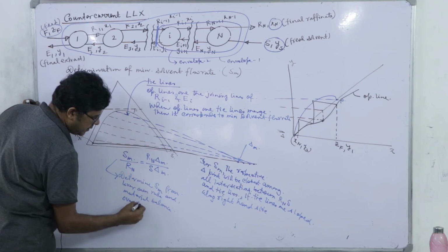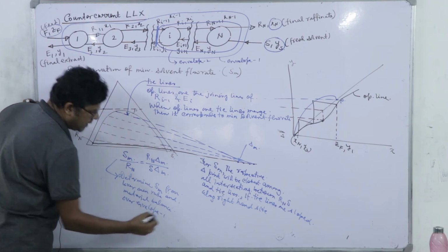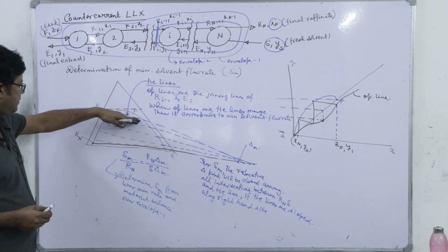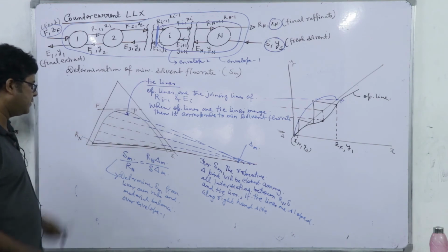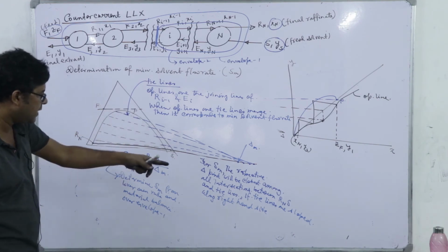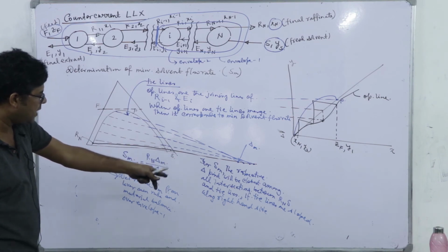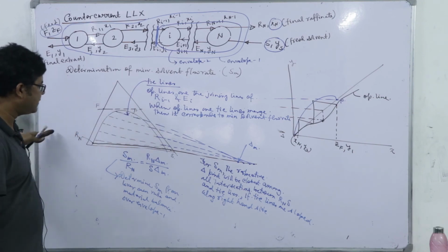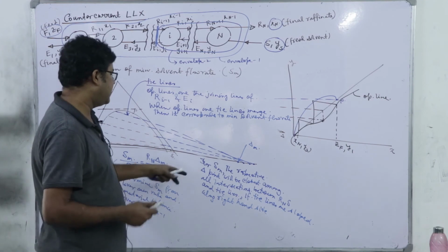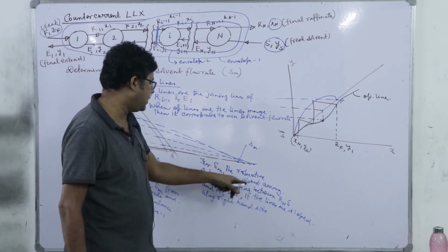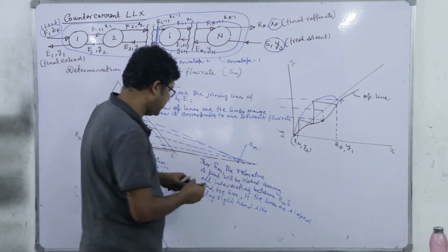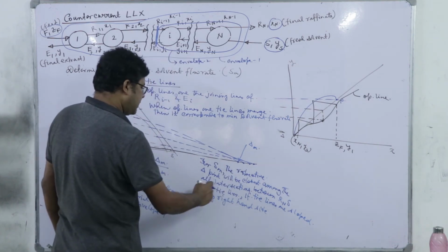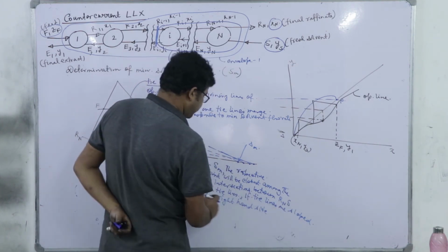over envelope 1, right. And alternatively, if the tie lines are inclined towards left, so here the tie lines are sloped along right hand side. So, if it is sloped along left hand side, it will be the farthest one, right. So, for SM the respective delta point will be closest among the intersections, right, between Rn, S and tie lines if the tie lines are sloped along right hand side.